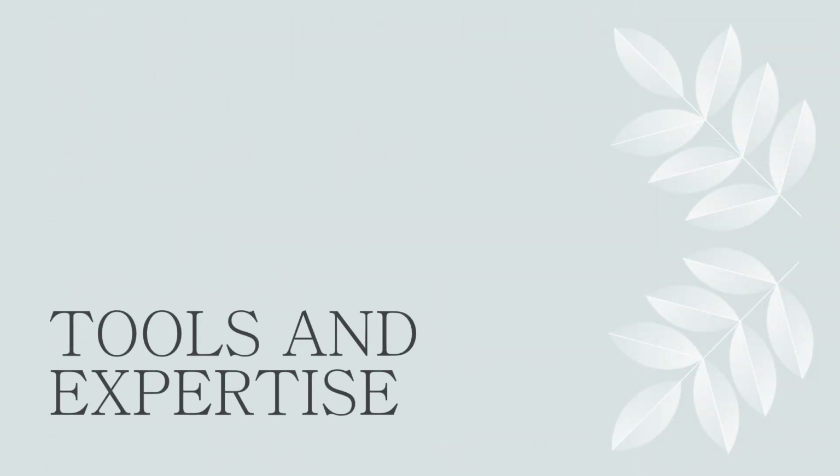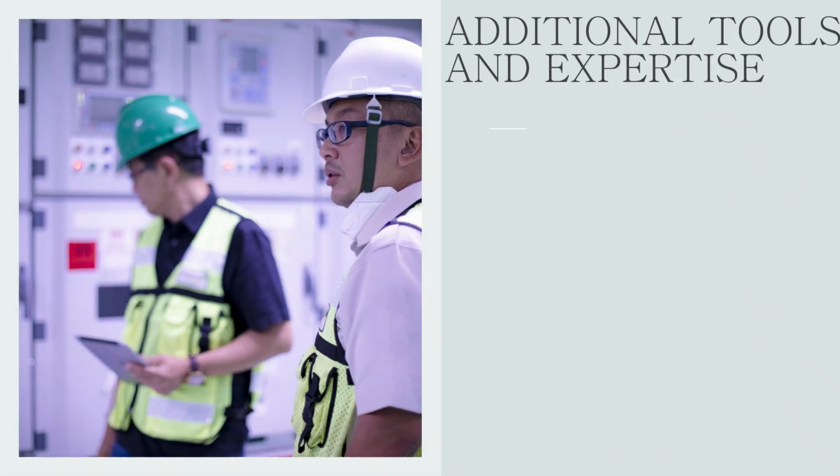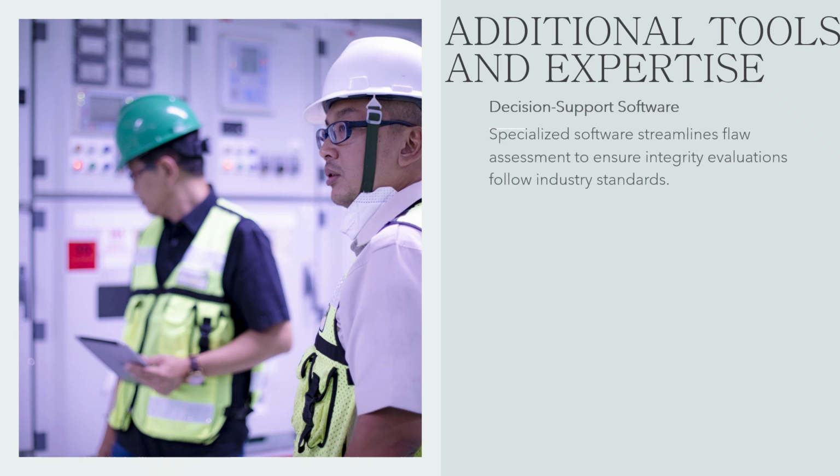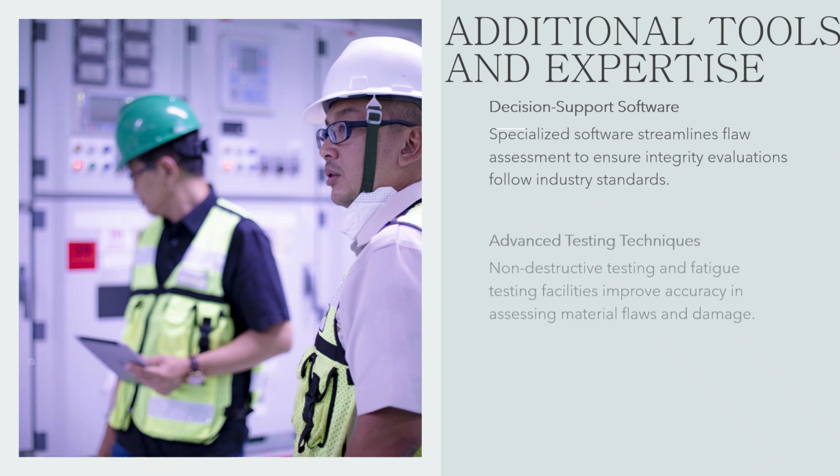Tools and expertise. Performing an ECA requires specialized tools and expert knowledge. Decision support software like CrackWise is widely used to streamline flaw assessment in accordance with BS7910. These software assist engineers in evaluating the integrity of pipelines, pressure equipment, and structures containing flaws.